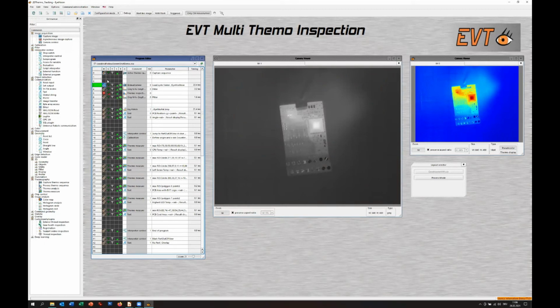So you see a small P and C in this column. That means these tools are only executed in process mode. That means if this changes to process, then this one is executed, and as long as we're in configuration mode, that one is executed. So you don't have to think about it. If you go to the machine and press process mode, then immediately it switches, not only to capture the image from the machine. Maybe you also have all the PLC I/O connected to the machine active, because you say, if it's in process mode, please also handle the PLC.